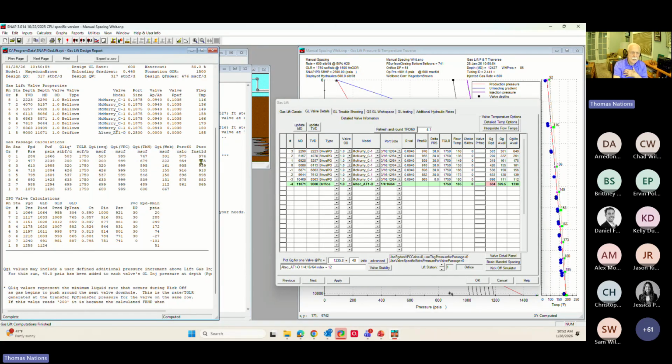And certainly down here, this is the output information. So based on this PTRO 60 column, here's the set pressures on the valves. We've chosen a 30 psi surface closing pressure drop for our valves, and that's the API recommended practice for gas lift designs using surface closing pressure drop methodology. That's what SNAP does. So here's PSC, pressure surface close. Now, that's the acronym that most of the industry uses. The API acronym for this is actually PVCD. This is PVCD. This is the downhole closing pressure.